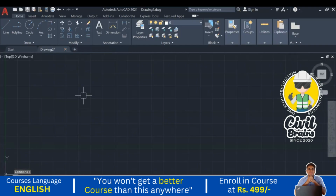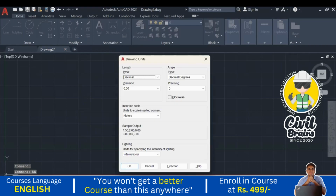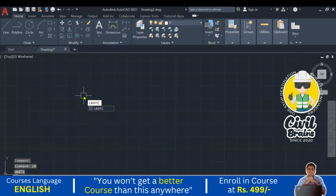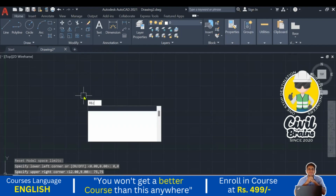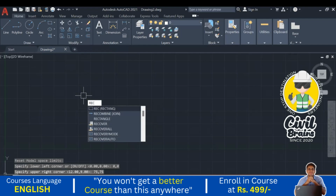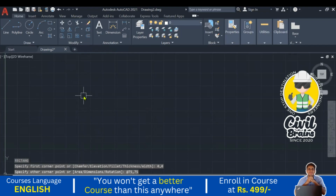So this is our new drawing. Units are set, I just check one more time. Okay, units are set. Limits, just type limits, press enter. First limit is 0,0. Next 75 by 75, enter. Next REC rectangle command, 0,0. Next 75 by 75, enter. Next command zoom, enter, all, enter.